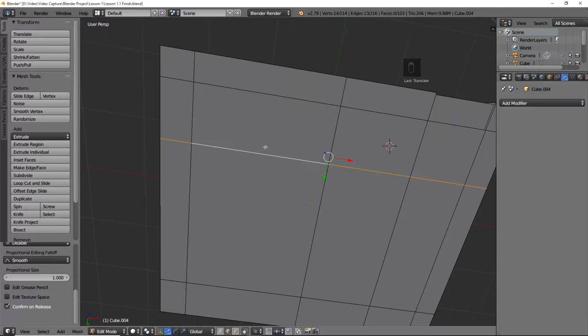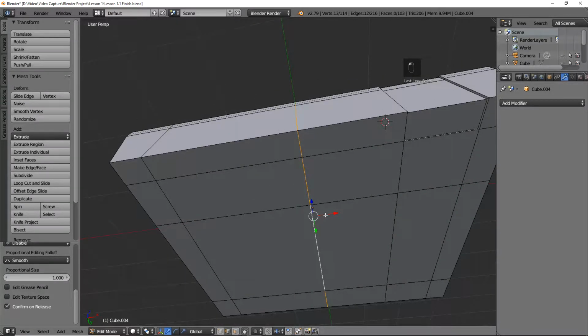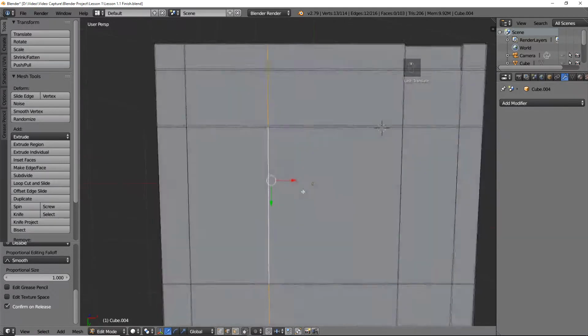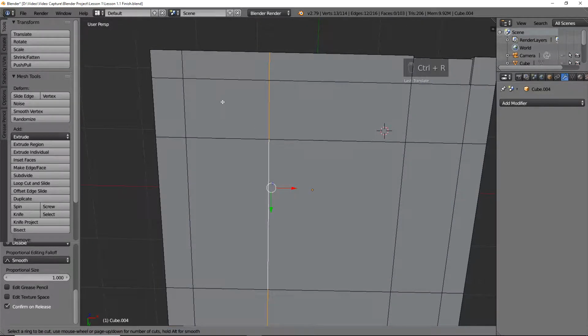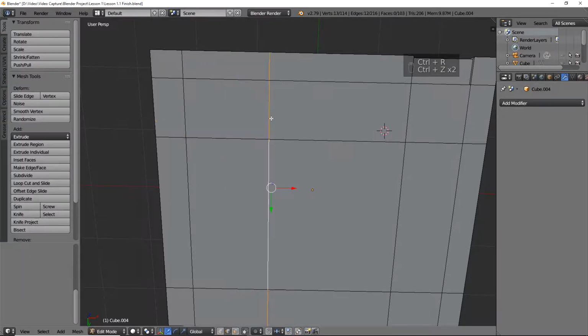So we want to place our line not at the edges but in the middle, because we're about to use bevel to create two edges out of it. So we'll go back to our model and we'll select the edge in the middle, move it to the left, then we'll create a few more edges here, and these will be to shape the rectangle in the middle.